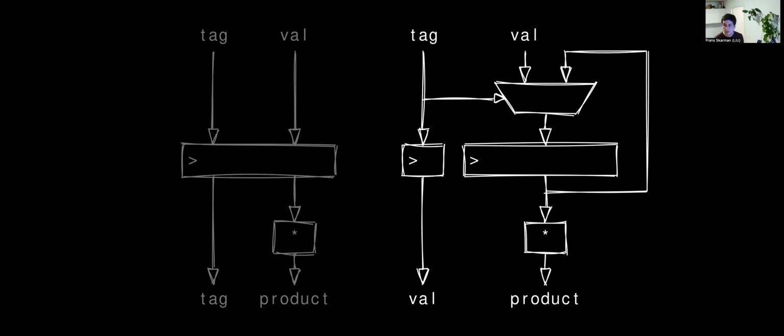Yeah, I think that's also an advantage of lifting things from Verilog. There are intricacies in how you should write certain structures. Like Xilinx even have a way of converting clock gating descriptions back into enable signals and stuff like that. And so I think it's nice to lift the abstraction from just inferring a register to being explicit about it being a register, because then the compiler can emit the correct register code for whatever platform you're targeting.